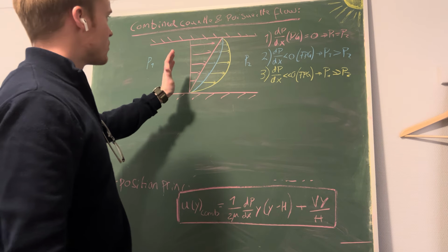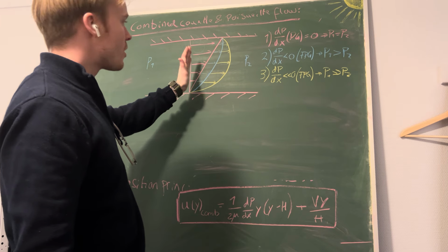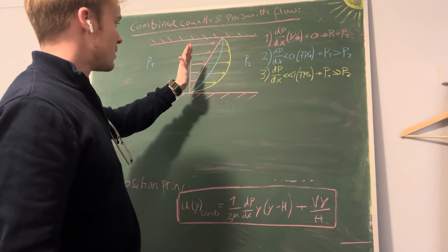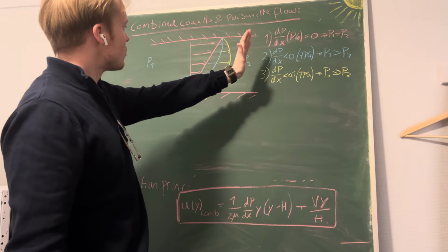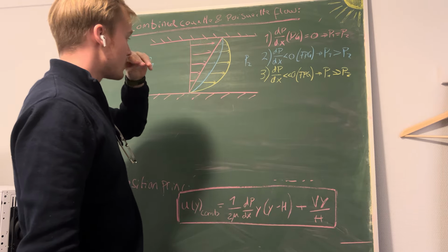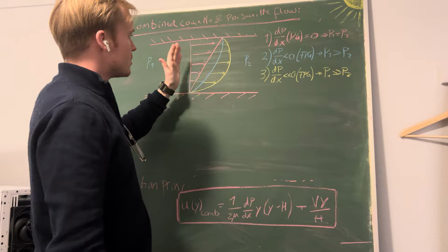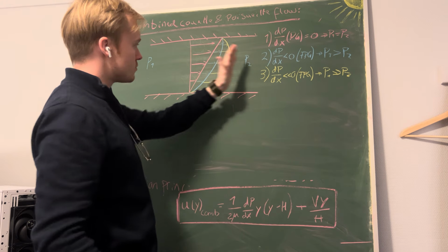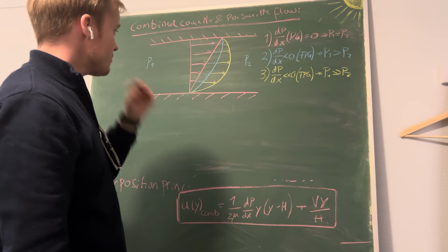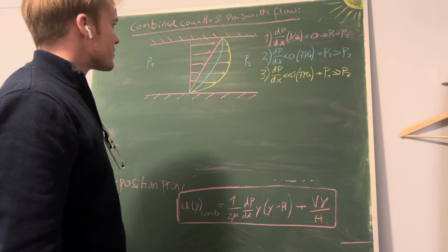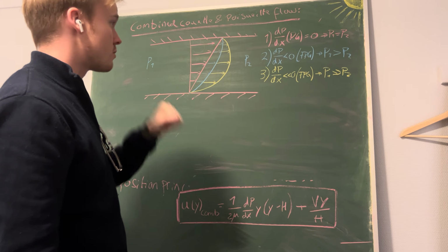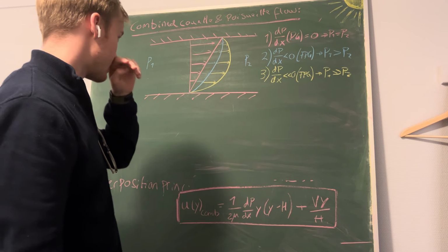So we see that when we are making a more and more powerful favorable pressure gradient, we are basically pushing more fluid through the section, and we're also bending this velocity profile to the right. So that is one case with a favorable pressure gradient.